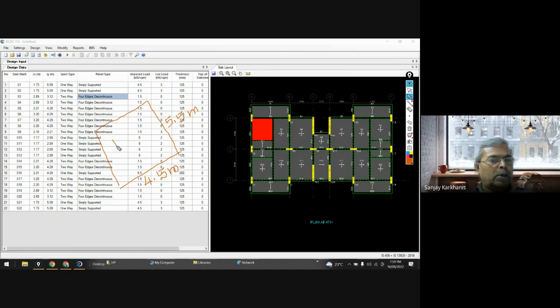And the live load that you are supposed to provide on this, as it is commercial, may be something around 5 kilonewton. In that case, your MU will be very high. From the strength criteria, or bending moment criteria, you might need a slab depth of something around 200, and from the serviceability criteria, you might need 150.